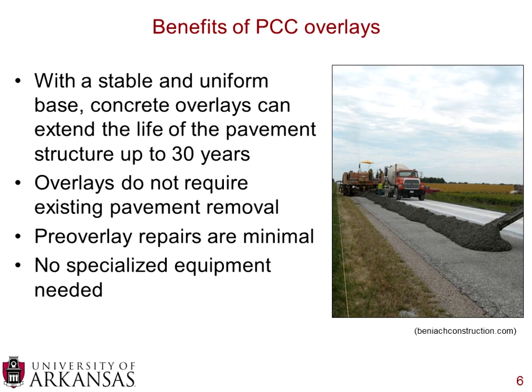One of the benefits is if you have a pavement that has pretty significant surface distresses, you don't need to remove any of the existing pavement. The overlay can simply be placed on top. And along those lines, although you want to make sure you are structurally sound, the pre-overlay repairs are minimal. So if you're structurally sound and you have a highly cracked road or even a rutted road, the industry believes that you need to do minimal repairs on those in order to bring it up to the level where the overlay can be placed. A benefit of it is also no specialized equipment is necessary.